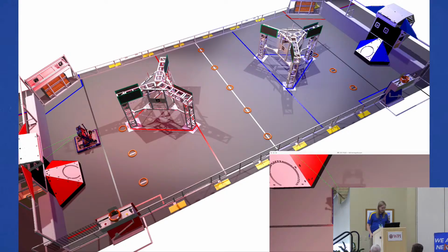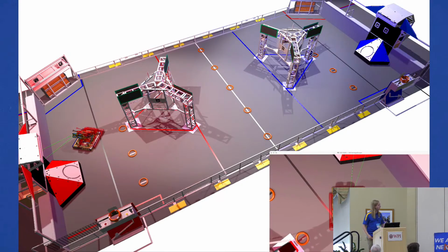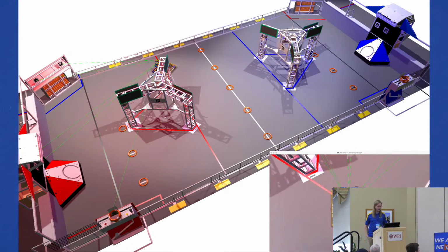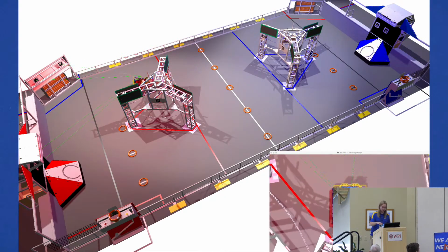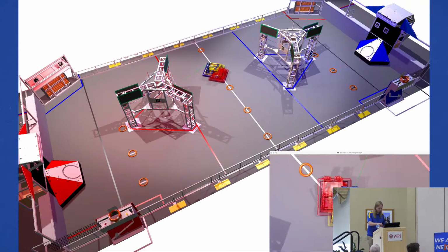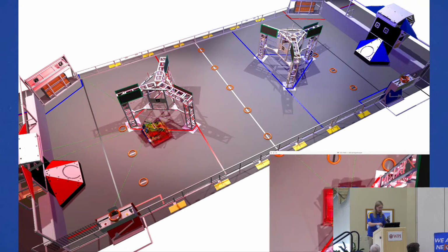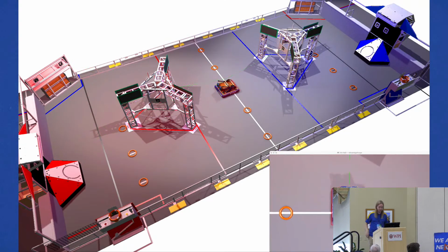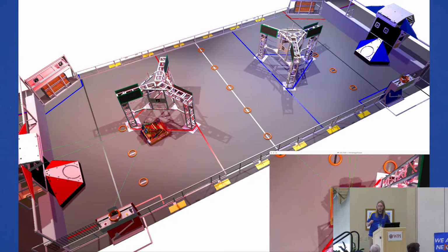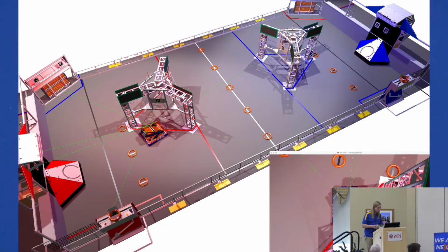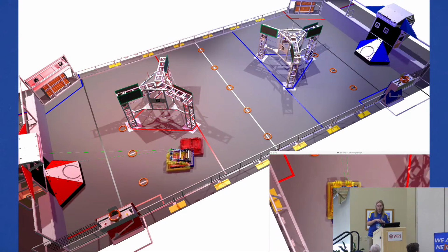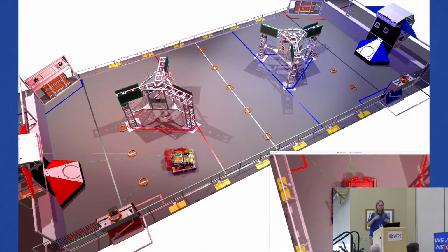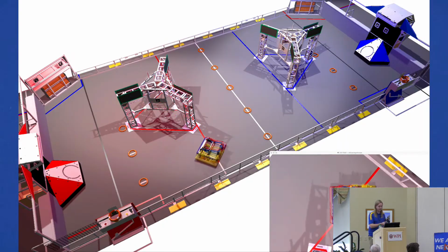Okay, now finally, here's just a fun example to show the importance of why we do all of that filtering and focus on having a wide field of view with multiple cameras. This is from our first 2024 event. So in the center there with the real solid robot, that's with all 4 of our cameras, all of our normal filters running. The yellow robot here shows if we only had 1 camera, but with all of our standard filters. So you can see that becomes offset when we're in a part of the field that we don't see a lot of tags.